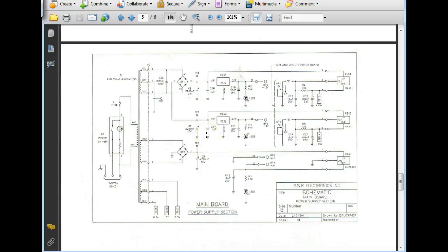Well, we polarize capacitors, especially in DC circuits, because the more farads you get, and I told you how we change the capacitance, we can either bring the plates closer together, but the closer we get them together, the lower the voltage we can charge them up to. So when they start dealing with higher working voltages, that means the plates have to get further apart.